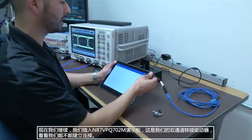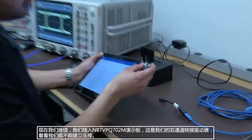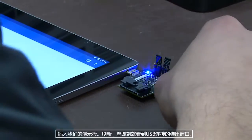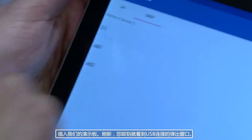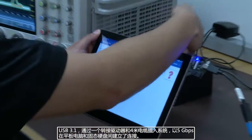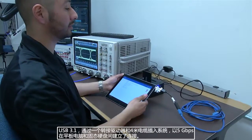Now let's go ahead and plug in our NB7VPQ702M demo board, which is our dual channel redriver, and see if we can establish a connection. Plug in our demo board, refresh, and immediately you see a USB connection pop up. A USB 3.1, 5 gigabit per second connection between the tablet and the solid-state drive was made with our redriver and 4 meters of cable in the system.